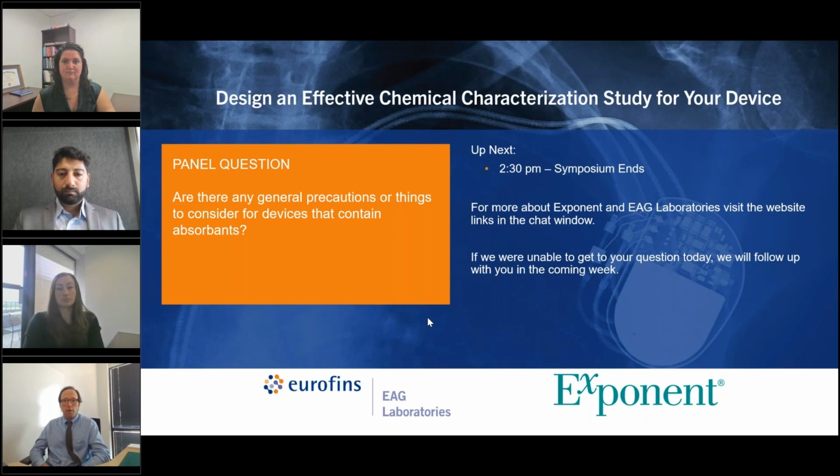So you've got to figure out what's going to give you enough to complete your analysis, but then you also need to determine how you are going to address the concentration, right? Because, for example, with the non-volatile residue, you decanted 5, technically that's only half of what was in that device, right? And are you going to consider it to all be in equilibrium and to be truly representative? Or will you do additional extractions to support that, right? And that needs to be considered on the front end.